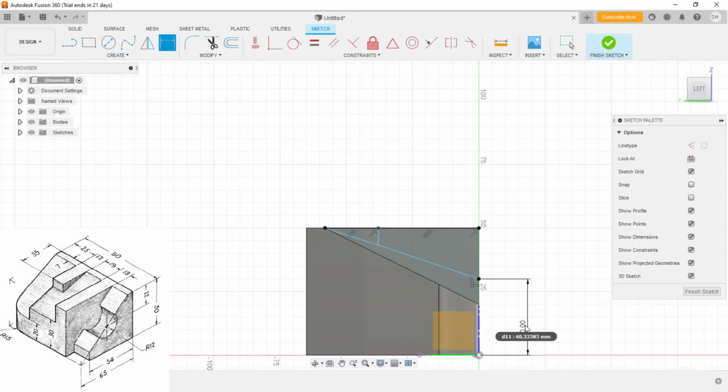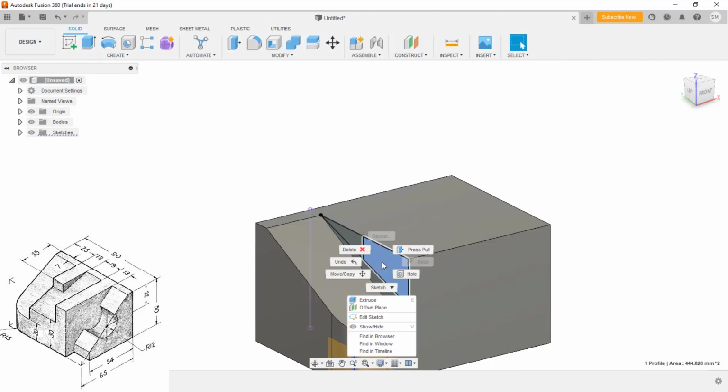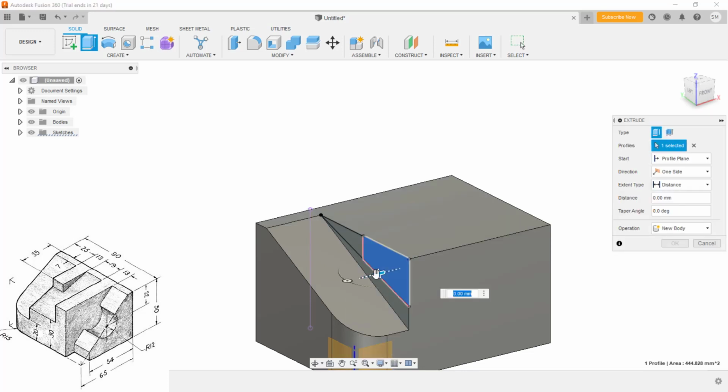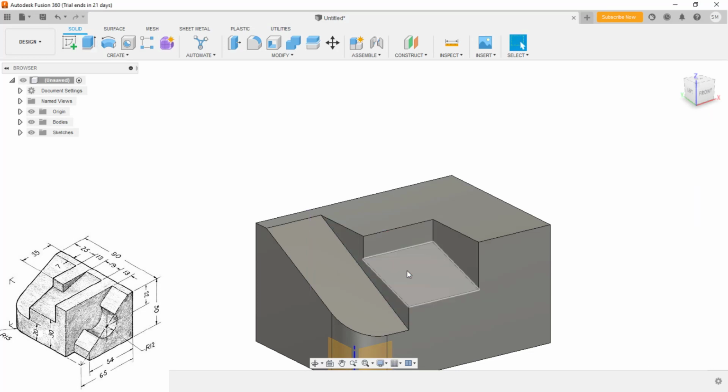You can even close it and define the dimension. It is 30 from the bottom. Yeah, this dimension is given, it is 35. These two lines are still undefined, select these two and collinear. Yep, fine, right? The sketch is even not closed, so we can select the contours, that is the best advantage here. I'll use the same method, so we can simply remove the material up to 25 plus 13 plus, sorry, it is 13 plus 19.